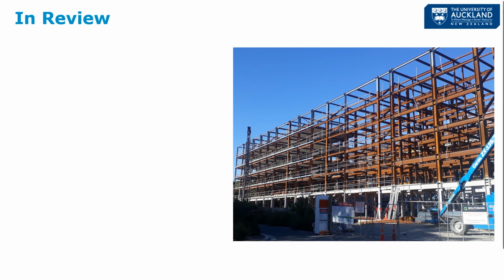So just kind of wrapping up with what we've learned in this video. First thing we looked at were the 2 main structural forms in NZS 3404 for the steel design in New Zealand, these being the braced and sway systems. And remember that those are going to be dependent upon what type of second order effects. Remember, second order effects are these P-delta moments, where the braced system is just going to be buckling within the length of the member, and so it's going to be a member type failure that we're checking for and designing for. And that for a sway system, it's dominated by these P-big-delta, so these are the total story drifts, so story movement, and so we're looking at a story by story failure. And that's because the column ends are not restrained in a sway system, and they can sway sideways.